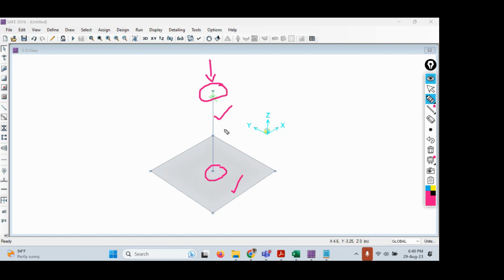But there is one more thing that applies by default, whenever you design any element, let it be the column or beam, whatever line element you are going to design. These are called line elements. Whenever you are designing line elements, in the CSI SAFE software or in ETABS software, by default the ends of the columns will be modeled as hinge supports.